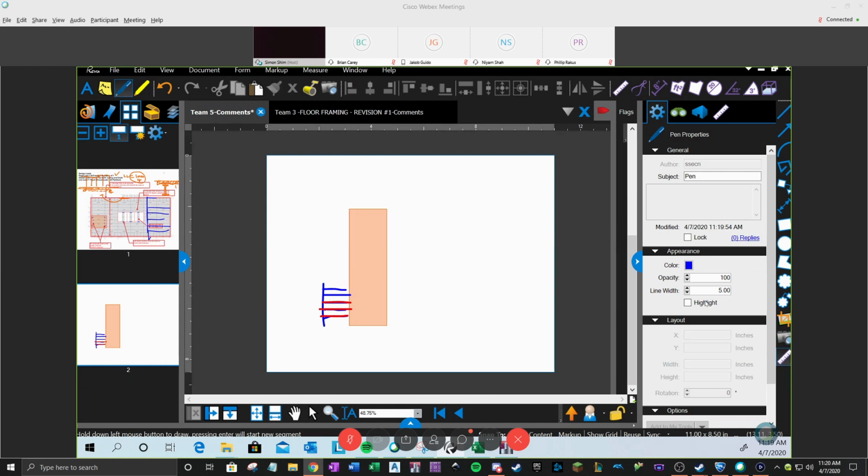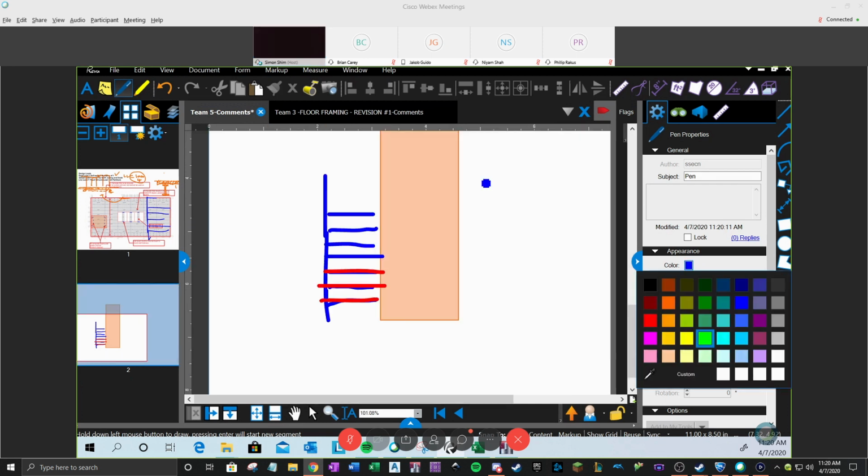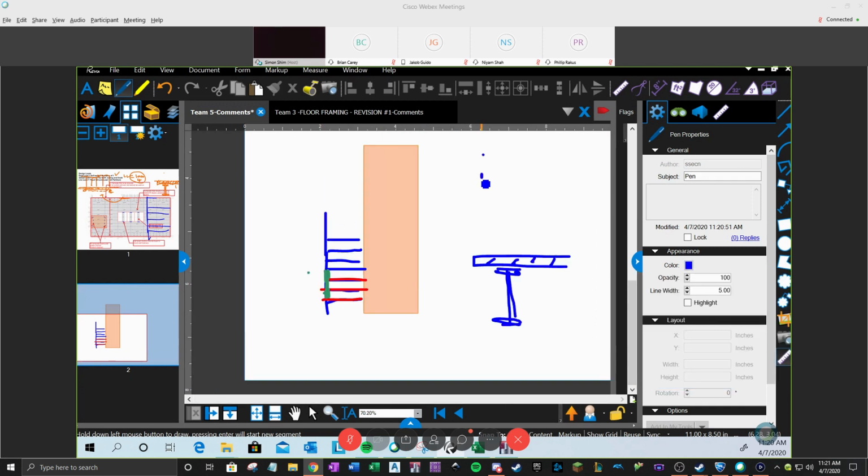Do you follow this, right? Now go back to the big picture. That is one. And after this, after erecting, they put the curtain wall, the panel system. We treat curtain wall typically as superimposed dead load.